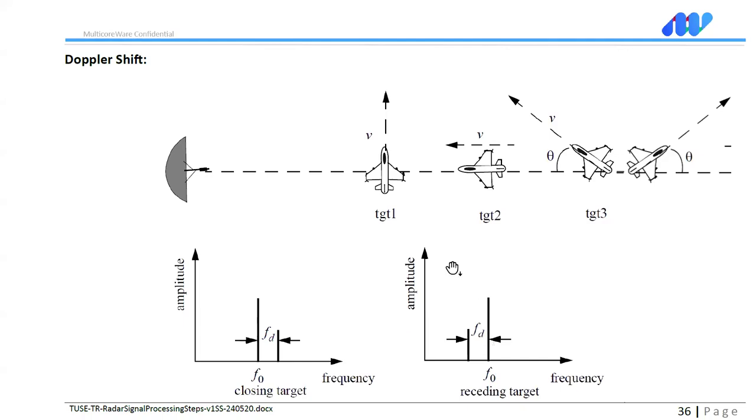But unfortunately, this doesn't work for all types of targets. For these, you're not coming towards them, you're not going away. So the radial targets will give you 0 Doppler. And further, these types of angles will make this Doppler shift smaller. So it's not like range processing. It will help you if the target is moving radially. So that's the measured Doppler frequency.